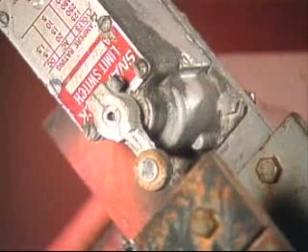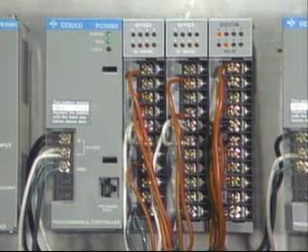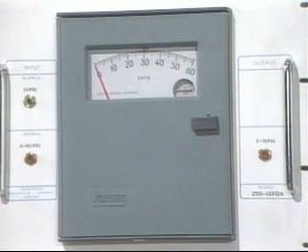In this type of system, the programmable controller detects the position of each switch, uses that information while evaluating its control logic program, and then sends a signal to the process controller that controls a specific piece of process equipment. This signal informs the process controller whether or not the equipment can be operated safely.